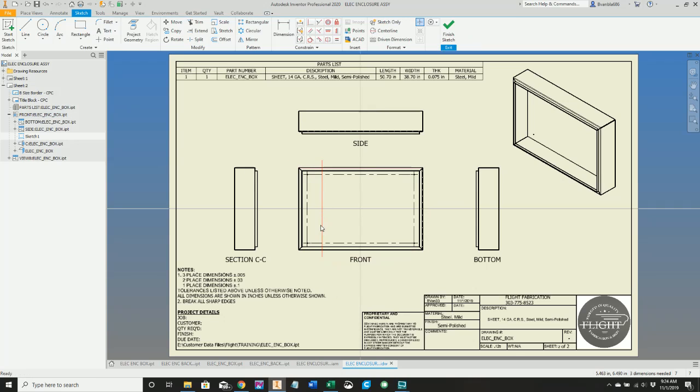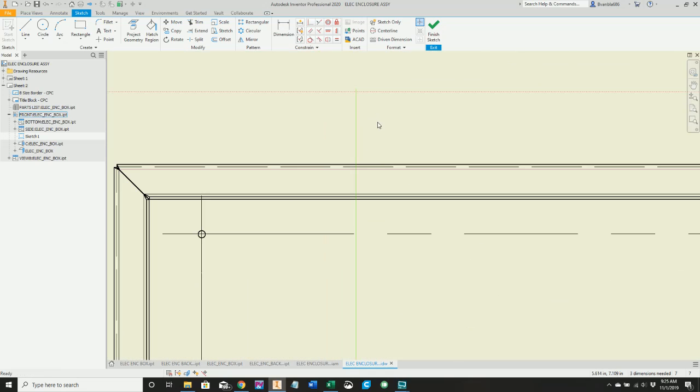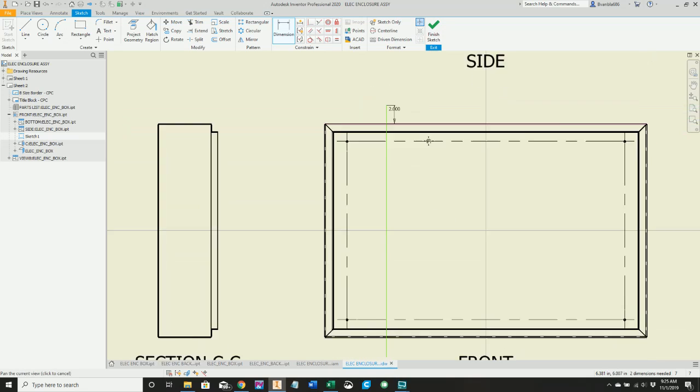And you can see that it's got a line here, and you could actually delete this, go up to sketch and create a whole other line if you wanted to, or you could have that line zigzag all throughout the entire thing. So I'm going to zoom up to this one edge here. I'm going to hit D for dimension, and I'm going to select the outside of the box, and I'm going to select the outside of the line, and I'm going to put 2 inches.